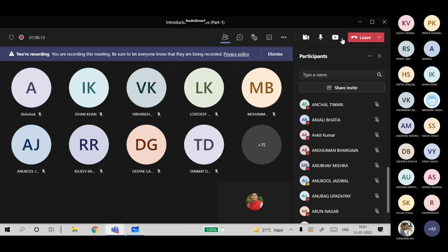It's an embedded thing, no? Fine. So the algorithm is running there. And to match the MAC address is very simple. You can have a small micro program with a register where the incoming MAC address can be loaded and a register where the existing MAC address is kept, and you can do a comparison in 1 or 2 cycles. Yes or no? Okay. Yes, sir, got it.